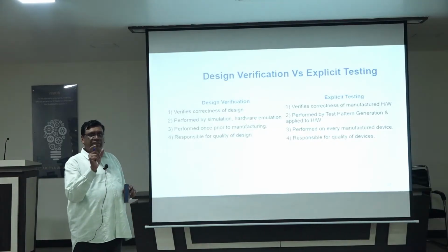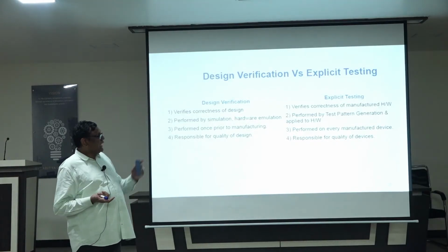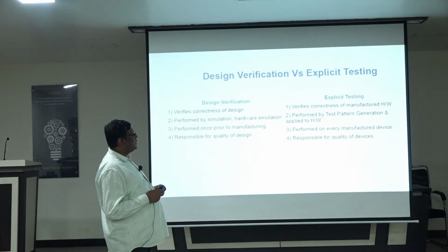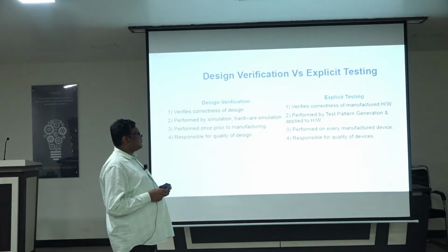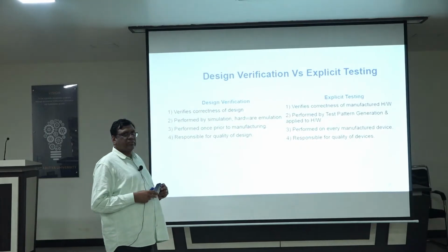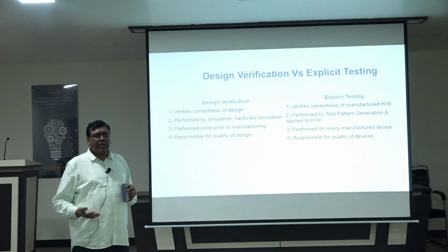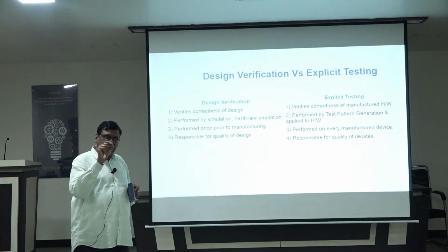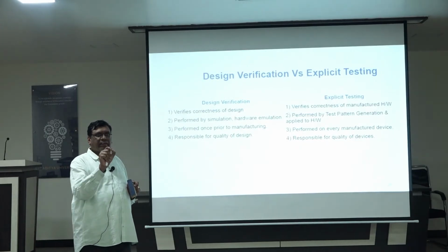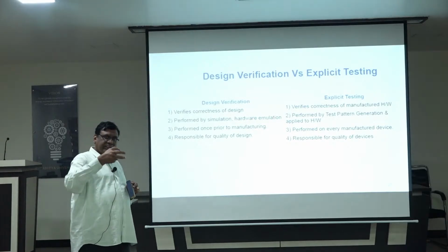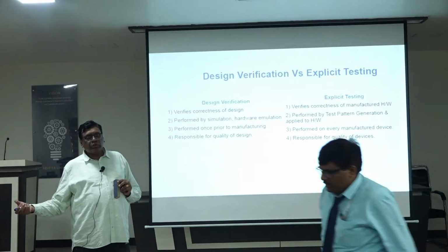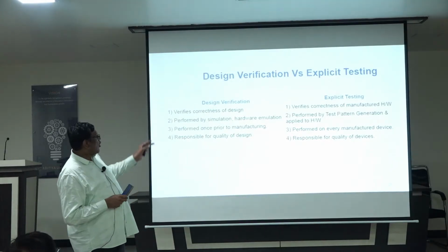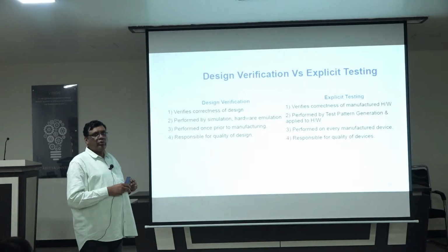After manufacturing, whether the hardware is manufactured correctly or not will be verified by testing. Verification is performed by simulation and hardware emulation, but testing is performed by test pattern generation. We generate different types of patterns that target a specific gate, a specific metal, a specific wire, and extract the information at the output. So very specific patterns are generated, not like the simulations you do in ModelSim.